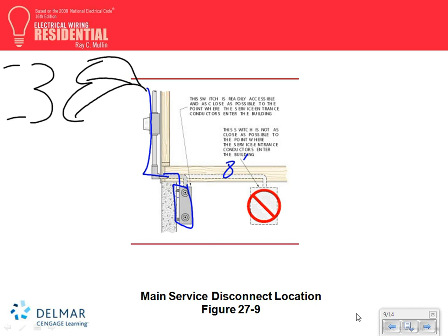Okay, when you look at the transformer, the conductors coming in, the only protection that they have is on the primary of the transformer. The only overcurrent protection that they have is on the primary side of a transformer. What does that mean? It means if I have a short circuit outside, who cares? There's a big fire outside. It's not going to burn the house.